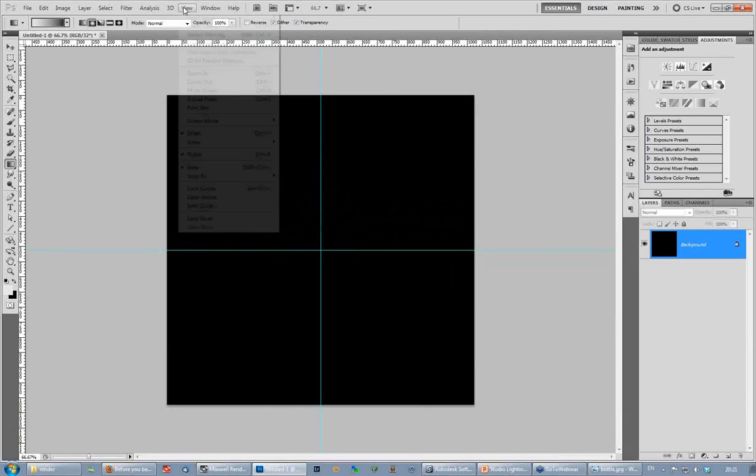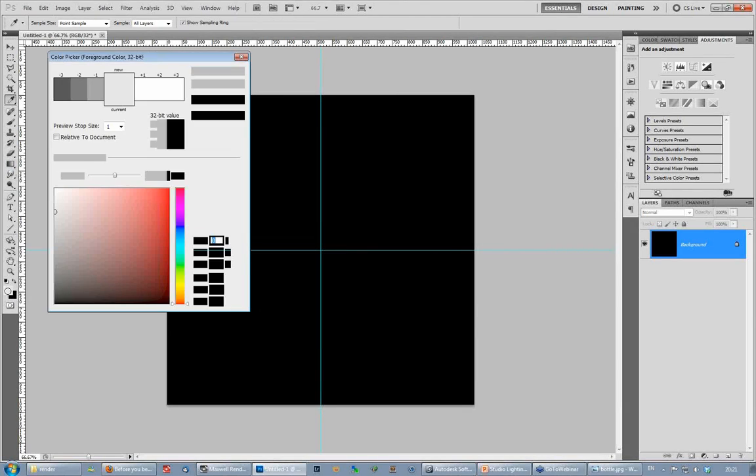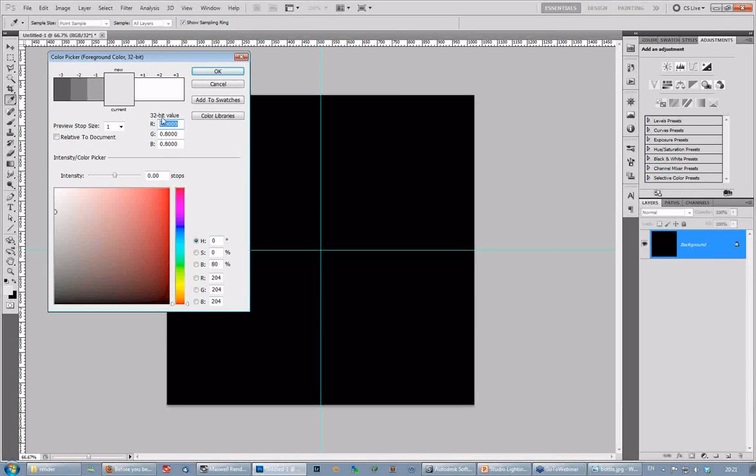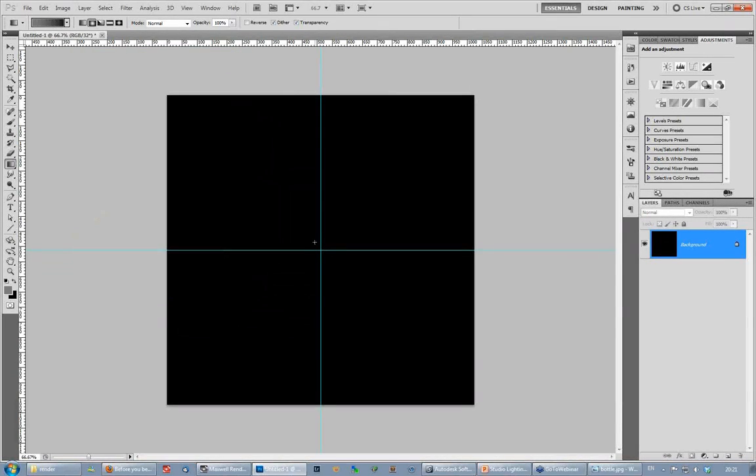And they snap in the middle because I have snapping turned on. And then switch to the gradient tool. And the important part here is that you first set an initial value here for RGB to something like 0.2. Okay, so this is going to be our base emitting surface. You'll see what I mean in a minute.